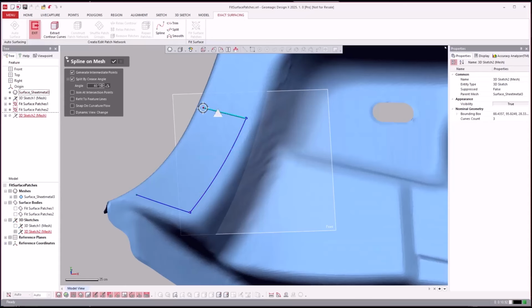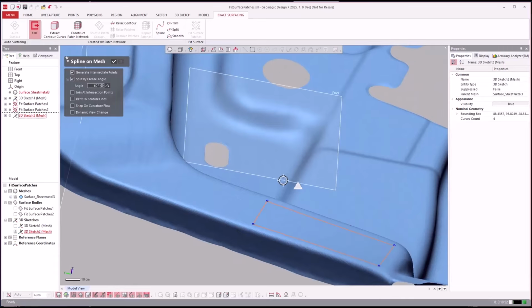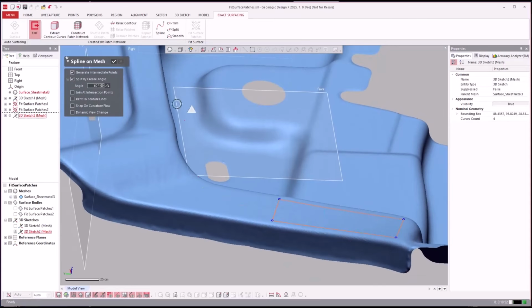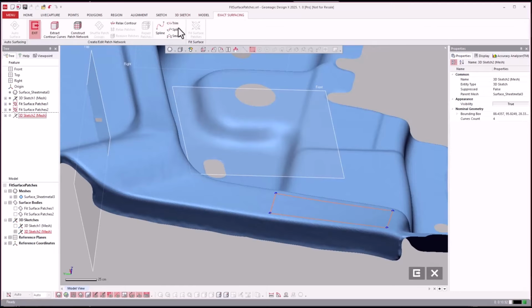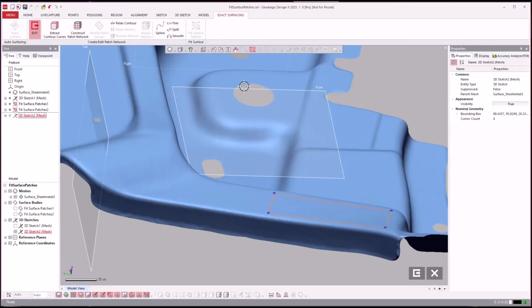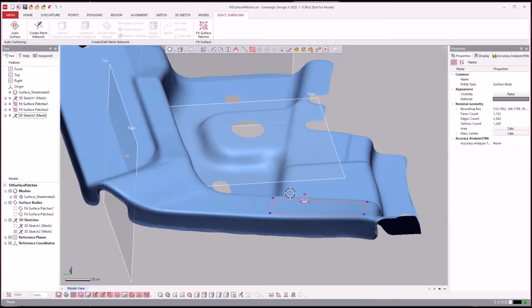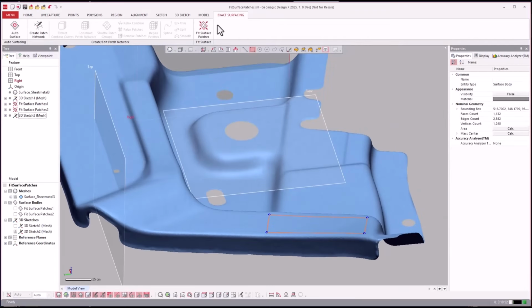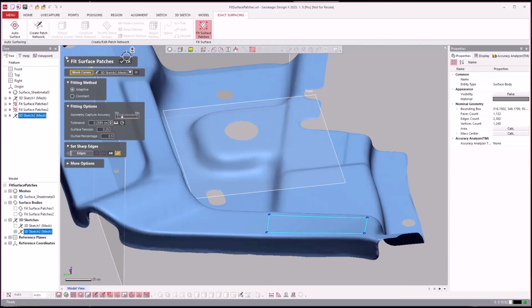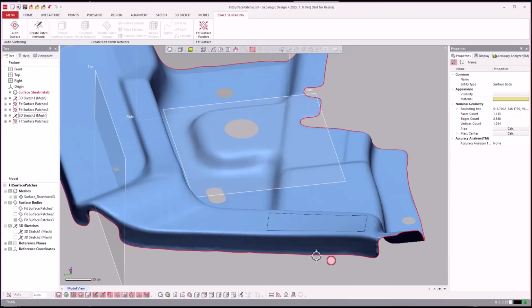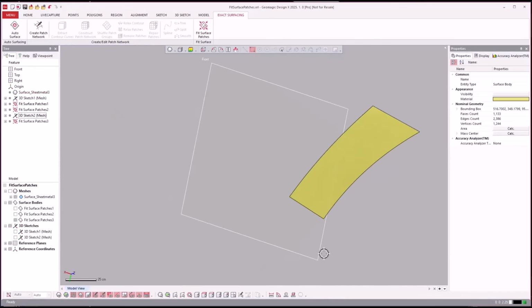In the past, you'll notice that I love using boundary fit surfacing a lot. And I've gotten this question from people many times: isn't that like redundant with the exact surfacing in here? And in the past, if I drew out curves that didn't envelop the whole shape, and then I came over to fit surface patches, the surface patches would not fit very well. So I would use boundary fit surfacing because that's a better way to go about it.